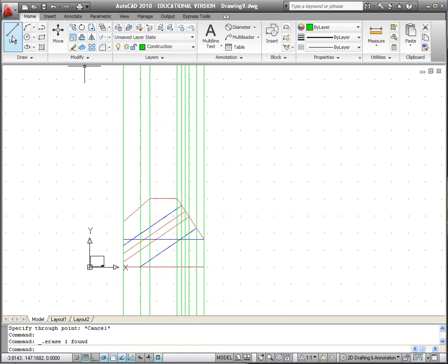So if I look at my upper view, I'm going to go and draw my visible stuff first. So I'm going to select the visible layer, come up here, select the line command, and then I'm going to draw across from here to there. This is one of those deals where you can go past and trim. It may be better for you to do that. So I've got that one set up, or you can turn on ortho. I've got that one set up.